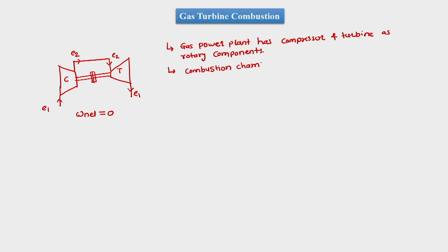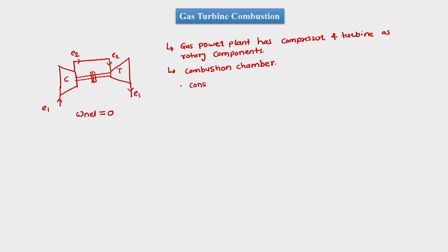In the case of the combustion chamber, there are multiple options. One option is as in our SI engine, where we use petrol or gasoline as fuel. The combustion in such an SI engine, which is based upon the Otto cycle, is at constant volume. So there is an option of constant volume combustion. Constant volume combustion is very effective and would lead to good efficiency when working with a given pressure ratio.